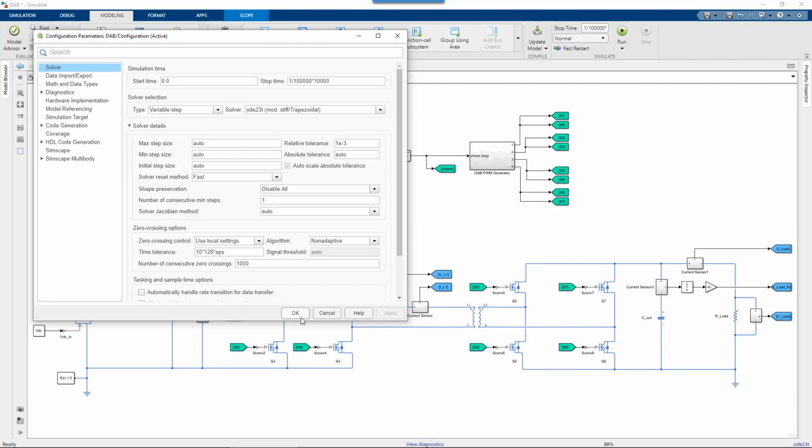But a trade-off is they all inject some sort of numerical error. Because of that, a lot of them, that numerical error will end up in decaying AC signals. So for an electrical simulation, we often have AC signals in them, so a lot of standard numerical techniques, their error is almost amplified in electrical applications because of the degradation and oscillation.